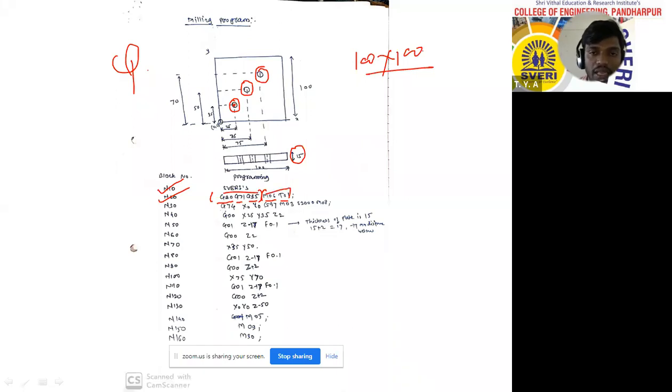Then next you can see reference x0 y0, again G97 constant speed, M03 speed value, coolant on, then direct operation start, rapid positioning x25 y35 z2. Why is this z value taken into consideration here? The question mark is here.